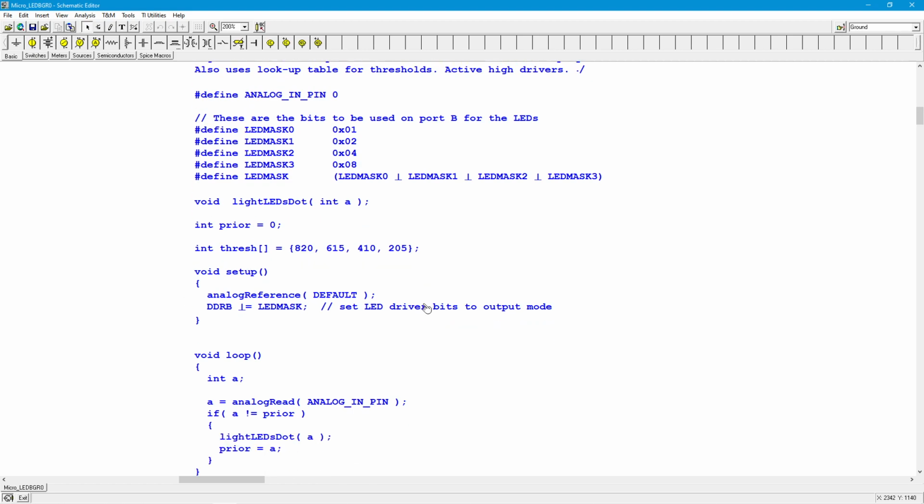Now, what I want you to imagine here is having multiple arrays, a threshold 1, threshold 2, threshold 3, and so forth. So you might have one that's, okay, I have a linear setup for this. I have a 3 dB logarithmic setup for this. I have a 1 dB logarithmic setup. I have a 6 dB setup. You could have bunches of these things. Then you could have some external pins where you have switches and so forth, and you can select which mode you want this thing to run in, okay? In our case, I just have the 1, and I'll point out where we would sort of monkey with this for different kinds of modes, okay?